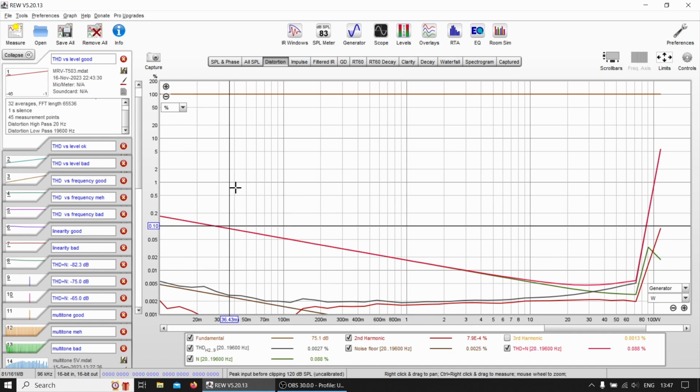If you have an amplifier with THD of 0.01, it's an excellent amplifier, amazing amplifier. If you have something even lower, like 0.002 or 0.001, this to me personally is a top of the range, top of the class amplifier. So far I've measured only one that measures so low, and that is an Alpine PDX.